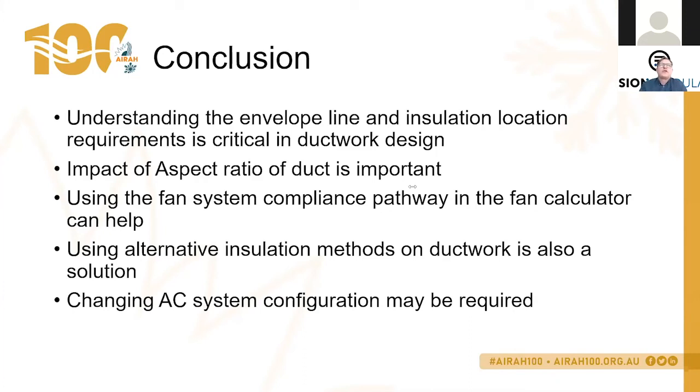If you have a rooftop ceiling plenum or rooftop ceiling space, that the insulation is applied at the ceiling line and the roof is only partially insulated or not insulated much at all, then you have a non-conditioned space for that ceiling void. So there are instances where you will have a non-conditioned space for that ceiling void, but it doesn't occur too often. Apartment buildings, particularly townhouse style developments or aged care developments, etc., do tend to have ceiling spaces that would most likely be considered not in the conditioned zone.